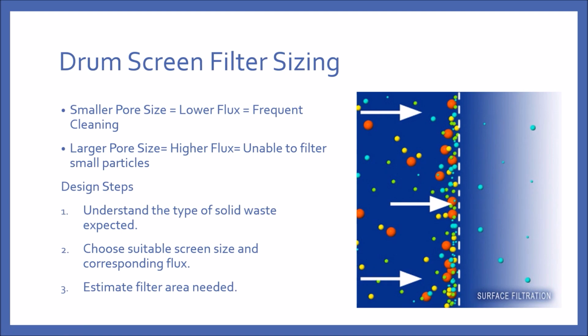Drum filters are used in the aquaculture industry, especially in the fish industry in saltwater processes. However, do note that a drum filter is usually more expensive as compared to the traditional media filter. There have been debates on the benefits and cons of using drum filters. One of the cons of using drum filters with formulated feed is that the formulated feed tends to disintegrate when it is rotating in the drum, further aggravating your suspended solid issue.